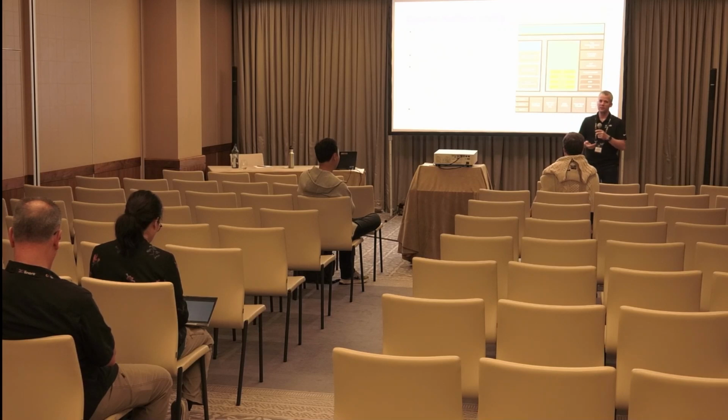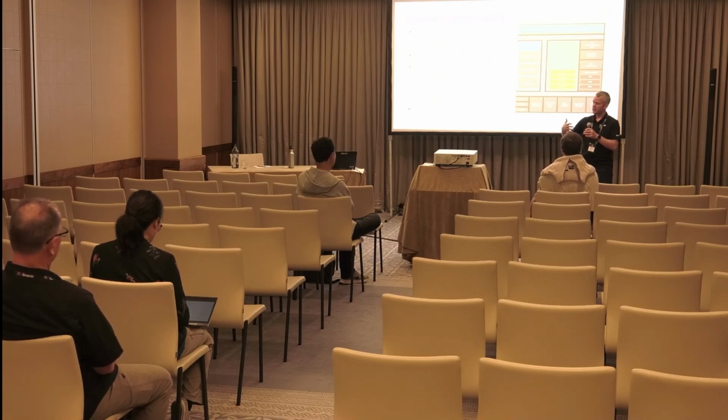And the other thing is these are typically module type drivers, so they only get probed at load. That's why I say loading generally works well. It's unloading where any of the dependencies that a driver had throughout the system aren't always unloading cleanly. So what we've had to do to date is a lot of testing, but you'll find that device tree ordering can start to matter.